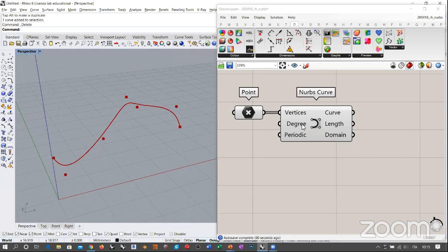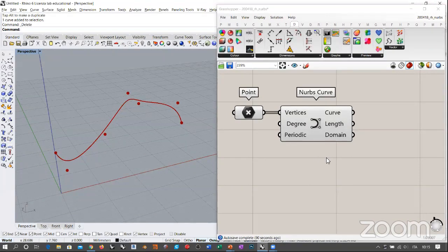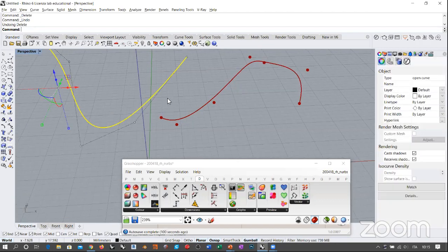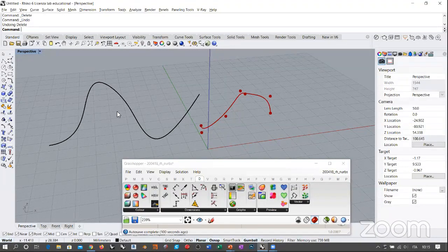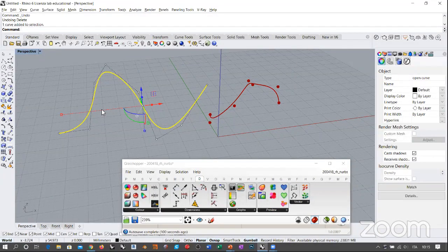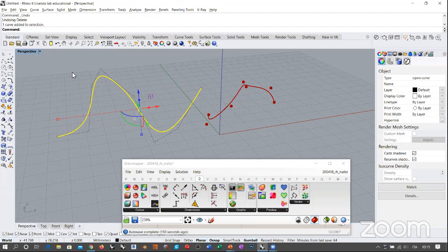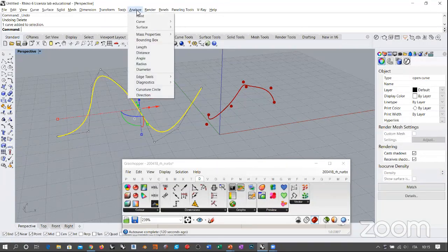Now, you see that this analysis is better for me because it gives us access to two particular properties of this NURBS curve, which is something that you don't easily understand or get in Rhino, because if I go back to this curve, in Rhino you can only handle the geometric property of this curve, not the topological one, at least not in a comprehensive way. So for example, if you want to, let's say, calculate the length of this curve, you easily have access to this